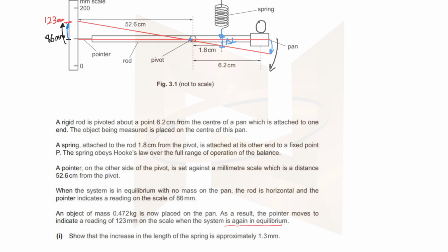And now how do we calculate this increase in length? An idea that comes to mind is that if I calculate this angle alpha, it should be equal to this angle alpha because they're alternate angles, aren't they? In those sides, the angle between them is alpha, and between the same two sides on the other side, it should also be angle alpha. It should be the same angle alpha on both sides. And why am I looking at this increase in length and not this one? Because they're asking for the spring. The spring is connected here. So the movement over here is going to be less as compared to the movement over here because they have the same angle. So the delta L here and the delta L here, those two delta L's will be different. And if the question in your mind is, why are these two different? Then please try to understand that the angle is the same.